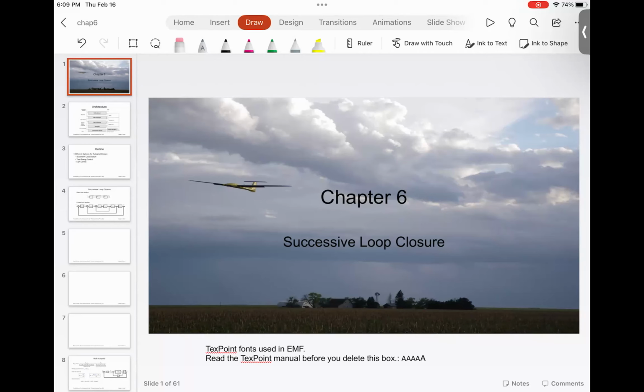It should not fall down. It should not tilt. If it tilts, it should be able to come back. If there is a disturbance around it, it should be able to overcome the disturbance. So first inner loop is always stabilization.